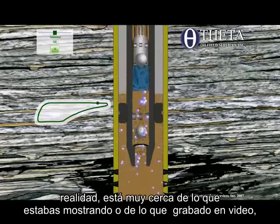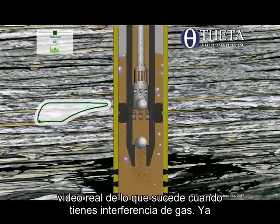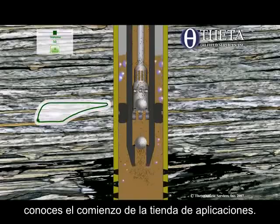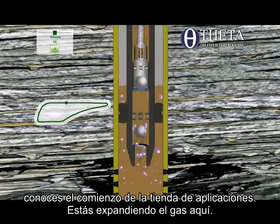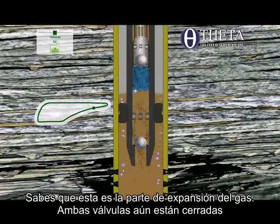It's actually very close to what you were showing, or what you videoed, right? Yeah, it's pretty close to an actual video of what happens when you have gas interference. You know, at the beginning of the upstroke, you're expanding the gas over here. This is the gas expansion part. Both valves are still closed.